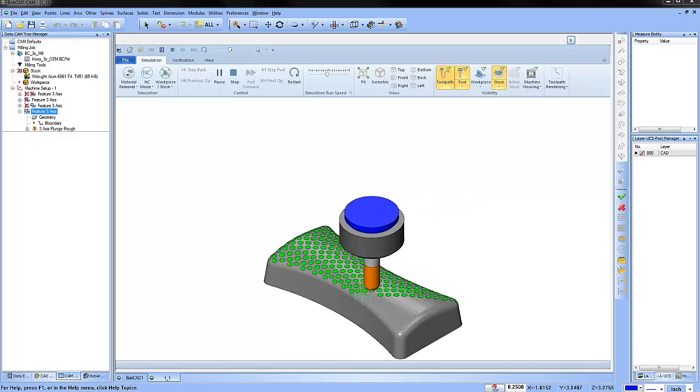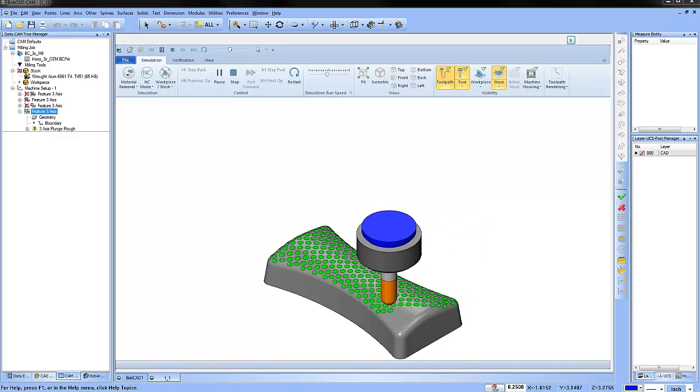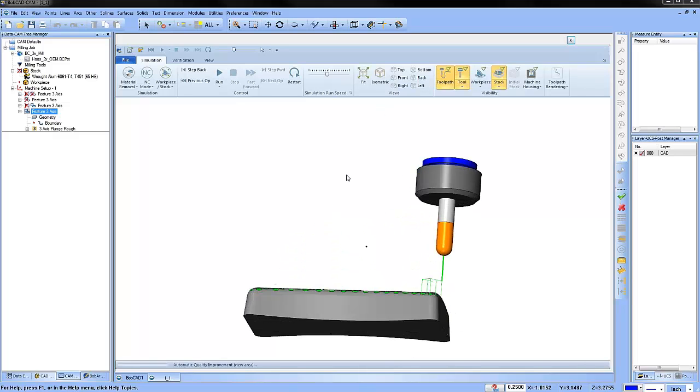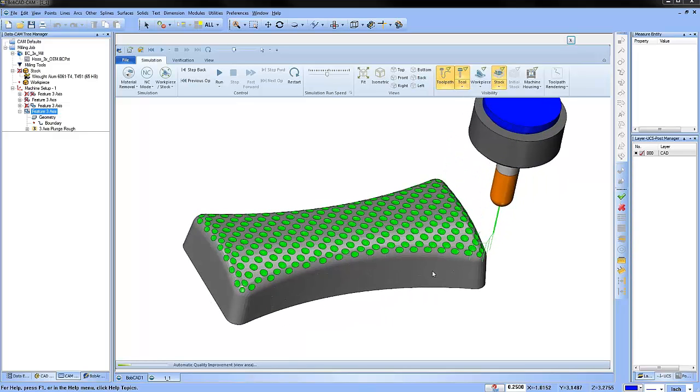But it really does depend on the application. So hopefully that answers your question there. Plus, you can Google all kinds of documents on plunge roughing if you want to get more of a history and some of the benefits. But again, usually you're using a larger tool. You just have downforce. You don't need the same RPM ranges that you do with the adaptive toolpaths.